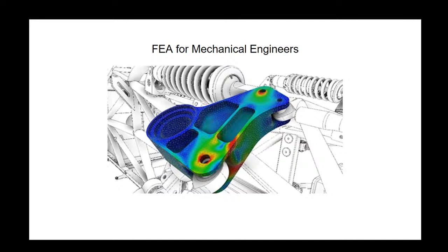And these elements are usually one of two different shapes. They're usually either a tetrahedron or a hexahedron. Then the solver can compute the material properties of each element that make up that whole model. And this way an engineer can see what elements in what part of the model are under the most stress and make decisions based on that.